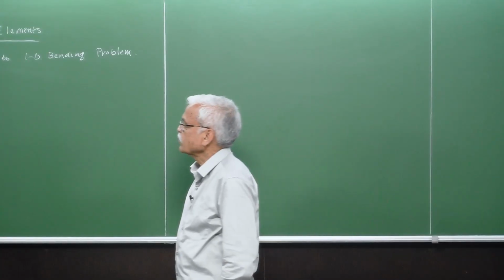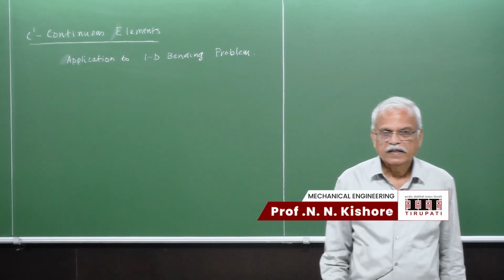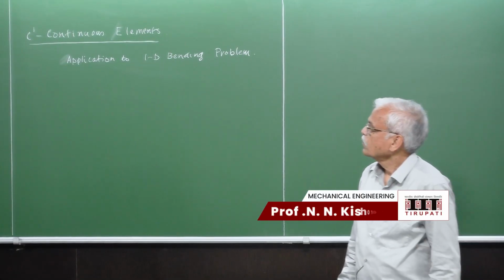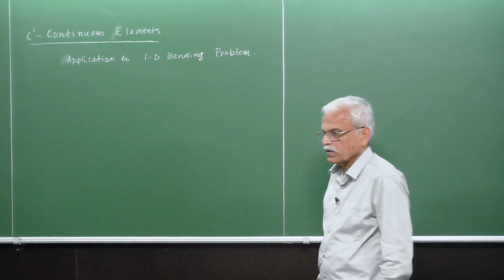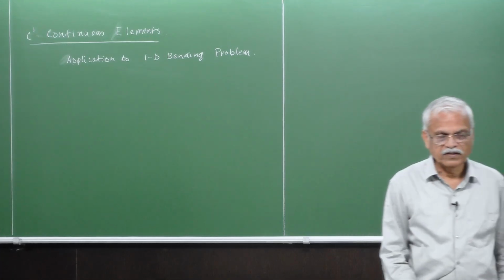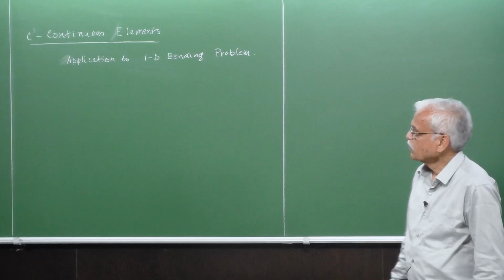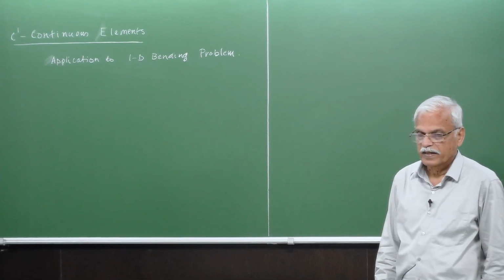Good morning, gentlemen. So now let's go through another important topic, that is the C1 continuous elements, where the approximation function is of C1 continuity nature. This is very much important in the case of bending problems.